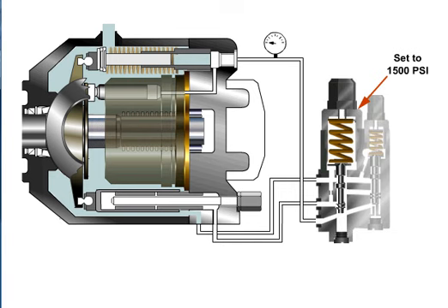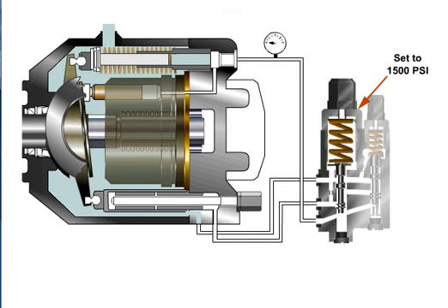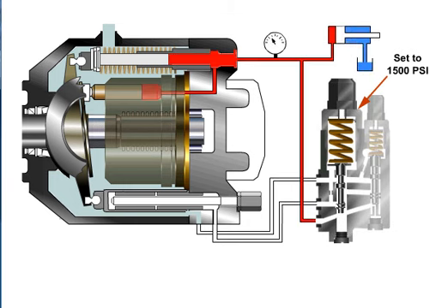It is helpful to understand the functionality of a piston pump. If you need to review this, return to the Pumps menu and go to the animation for the piston pump. As the pistons rotate around the shaft and follow the angle of the swash plate, they are pumping fluid out the outlet, which provides flow to move a component such as a cylinder.